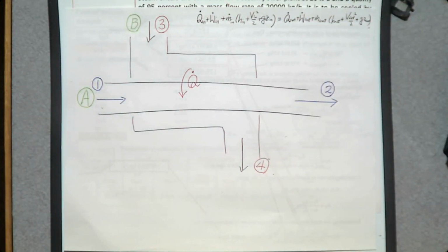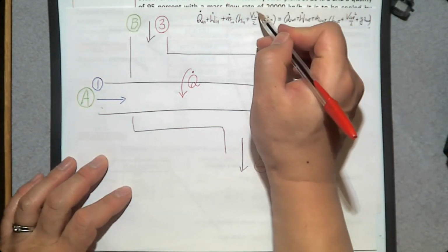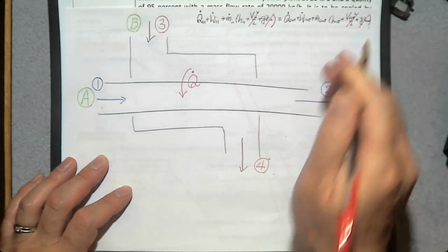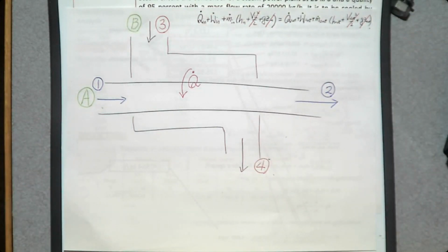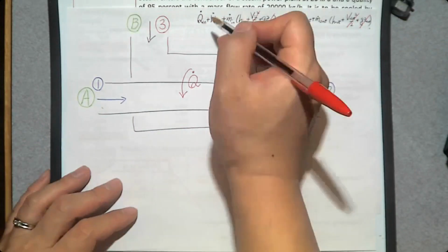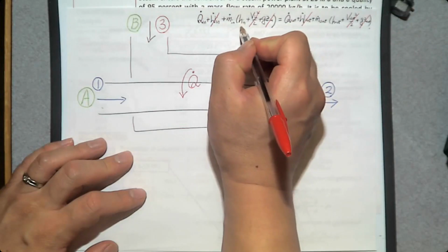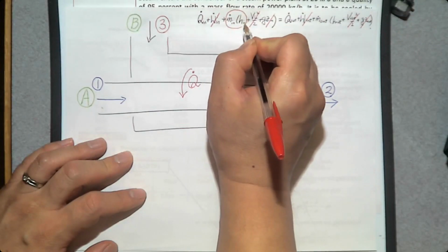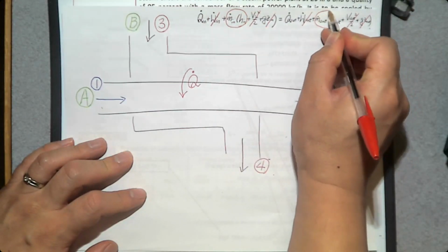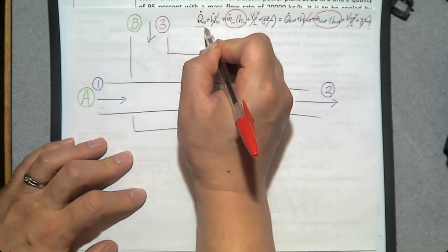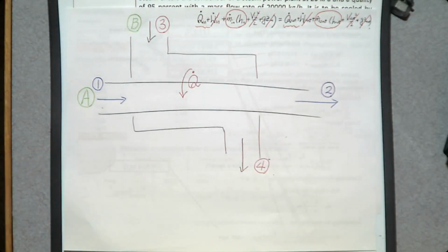And we can neglect kinetic energy change and potential energy change. In a heat exchanger, we usually do not expect any energy transfer by work. So you can neglect these two. So what we have? We have the enthalpy transfer at the inlet and its exit and possible heat transfer. Not both, one of them, depending on the direction of the heat transfer.